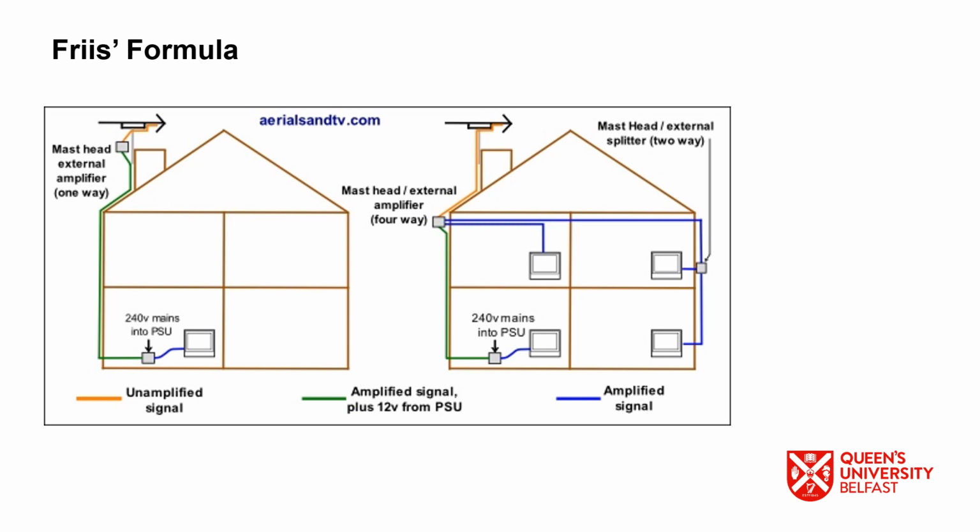Say in similar examples in which we have multiple cascade systems like this one and this one and this one, what we normally do is consider it as a standard cascade system, and using the Friis transmission equation we can identify how much equivalent noise temperature we are going to get at the output of this point, when the gain of these devices and the noise temperature of these devices is known from the datasheet.